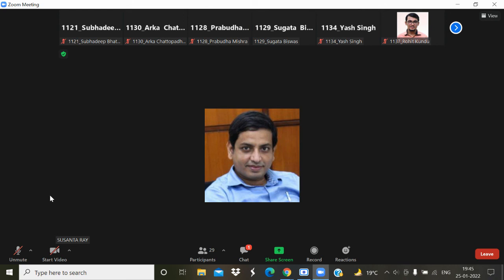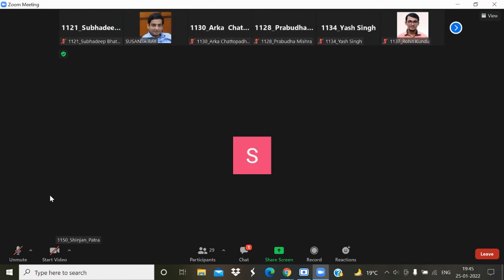So up to this, L and D, you have to calculate today. The rest of the thing you will start in the next class. Quickly, Faizan. So for 80 kilowatt machine, my D is 441 millimeter and my L is 415.442 millimeter.